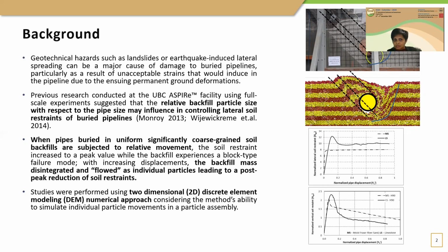What we noted was, when pipes buried in uniform, significantly coarse-grained soil backfill are subjected to relative movements, the backfill mass disintegrates and flows as individual particles, leading to post-peak reduction of soil restraints. So we decided to further study this matter. However, conducting experiments was not an option. They're expensive and time-consuming. Therefore, we decided to use a numerical approach.